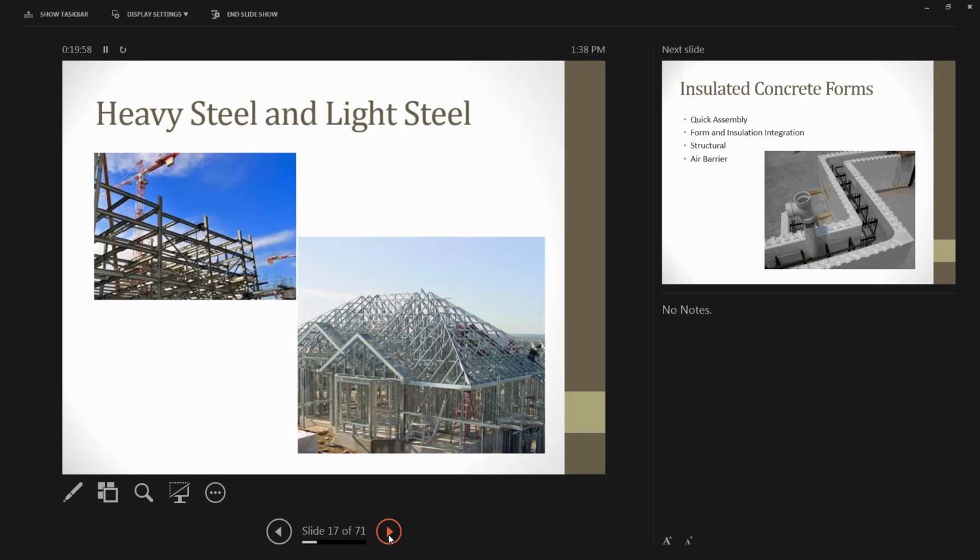I saw some houses where they didn't get a good enough thermal break on it, so you could see every stud line. If the conditions were just right, with the relative humidity and the temperature, you'd get condensation lines right down every stud. A couple of others had a thermal break, but they had their fasteners for the siding go straight through, and then you would see all of the little screw heads. So it's got some issues.